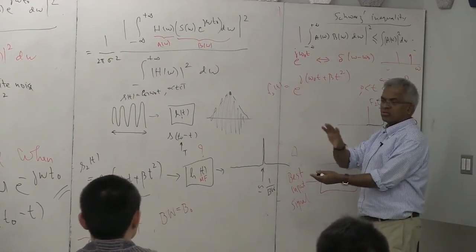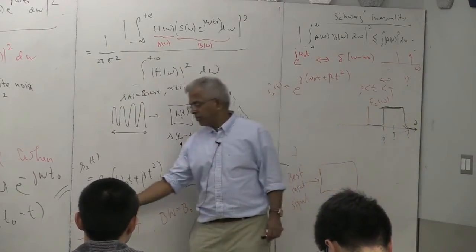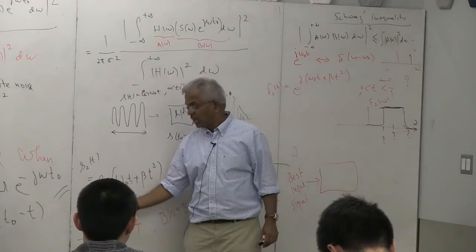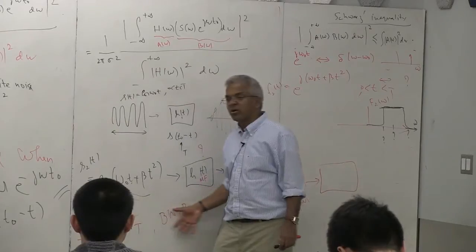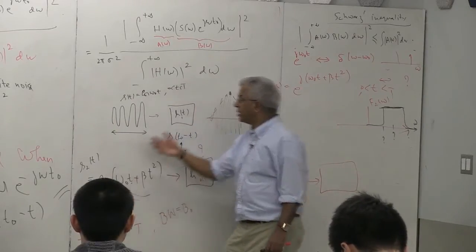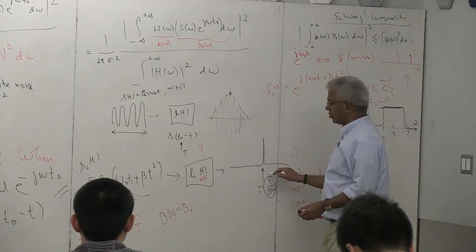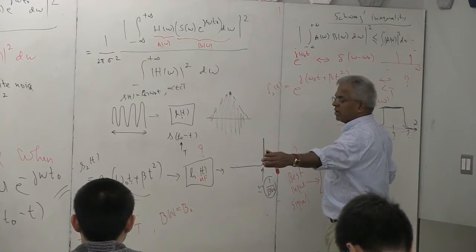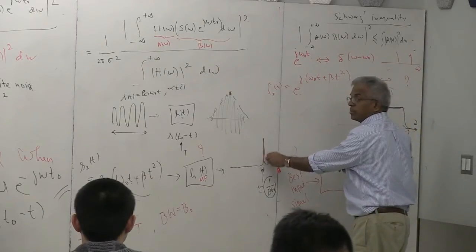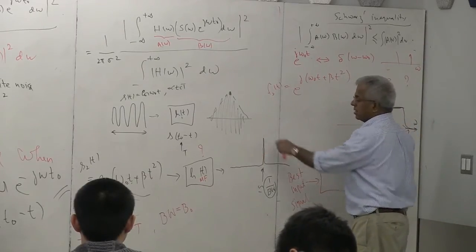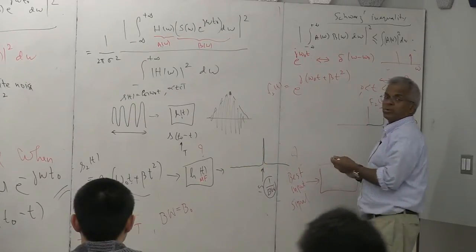Constant modulus, so even you can implement it at microwave frequencies. And look at here, if you transmit it for a long time at very low power, the output, as I said, is inversely proportional to bandwidth. So by keeping it over a long time, you're increasing the bandwidth, and that will make the pulse compress better and better. And this amplitude, I believe, is also proportional to the bandwidth value.